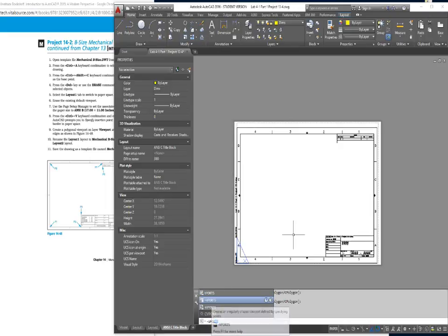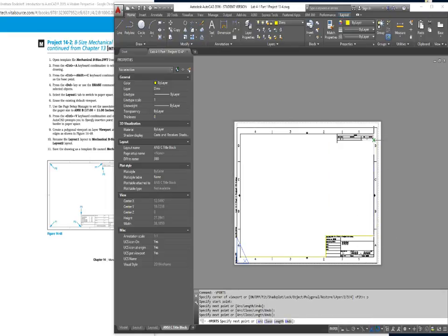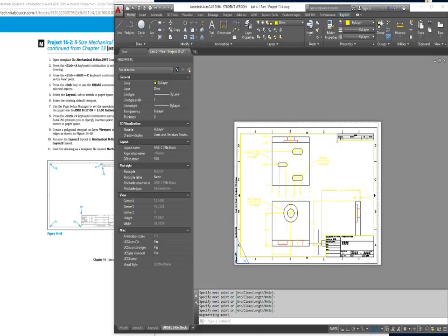Now look here. You have viewports. To bring up that dialog box, you have a minus and a plus. Okay, I'm going to do the minus right here, and that's going to give me these choices. You can either click on it or type P and hit enter. Either one will work fine. What this is going to let me do is draw from endpoint to endpoint or intersection to intersection and specify a custom viewport. And now I'm here, I right click and say enter. I've got my viewport in there.